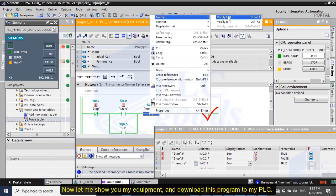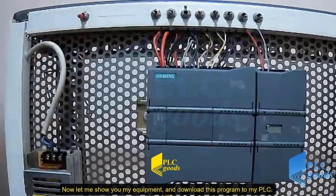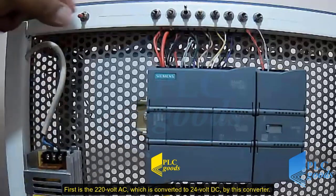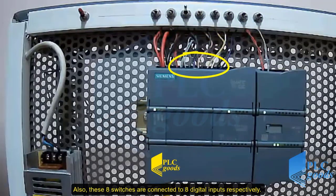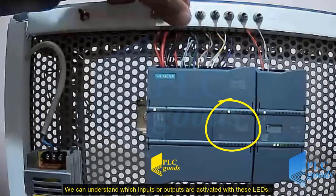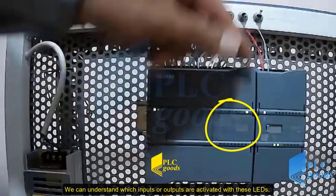Now let me show you my equipment and download this program to my PLC. First is the 220 volt AC, which is converted to 24 volt DC by this converter. Then my PLC can be turned on by this switch. Also, these 8 switches are connected to 8 digital inputs respectively. We can understand which inputs or outputs are activated with these LEDs.